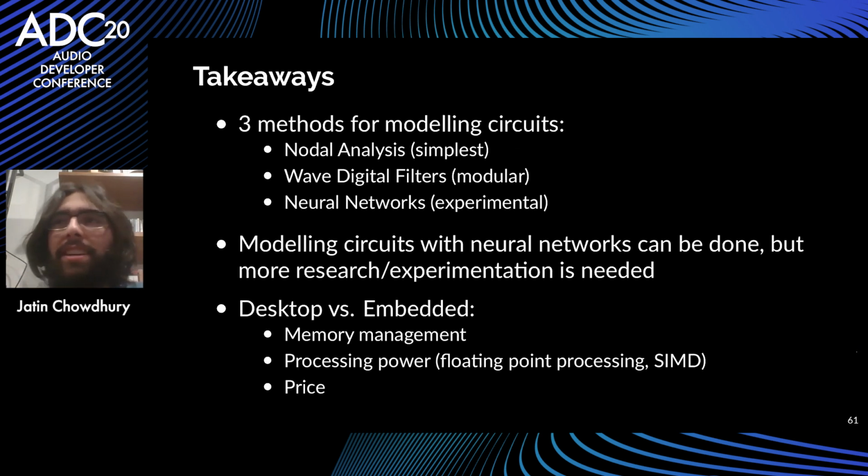Finally, I think that a lot of people these days who have been developing audio plugins on desktop are trying to move into the embedded space as well. And I noticed a few things that you don't really think about on the desktop that are very important in embedded. So one is memory management. If you've got a lot of neural network weights, you need to be thinking about where you're going to store those on your embedded device. Another is processing power. The Teensy has a floating point processor, but not everything does. So that's something to think about.